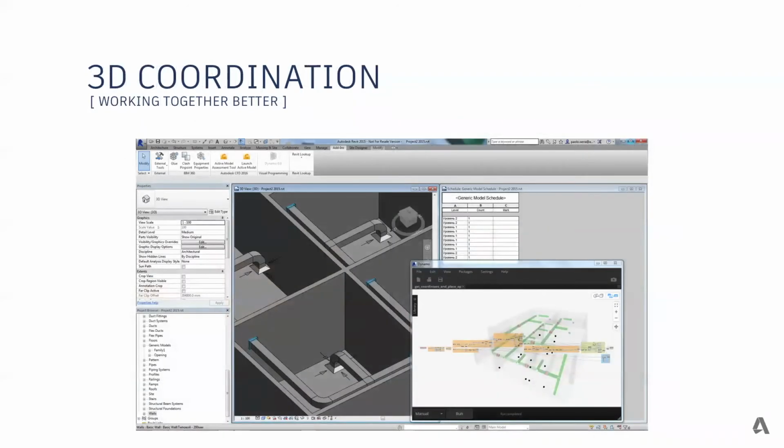We also have the ability to do 3D coordination. You do have technology such as Navisworks that you can use for this, but you can also build Dynamo graphs that leverage either the Navis API or direct clash detection toolkits within Revit itself to understand what is happening when some chosen category starts intersecting with another. So if we're talking about MEP ductwork going through walls, you can automatically understand those intersection points and automatically place not only openings in the wall but fire dampers based on the actual fire rating of the wall itself. So we're talking contextual awareness and modeling based on that contextual awareness.